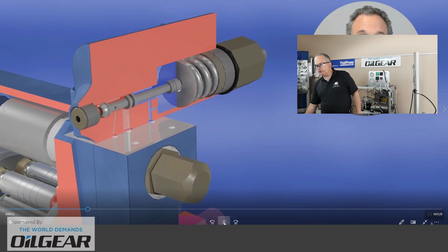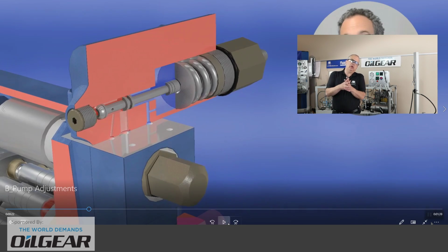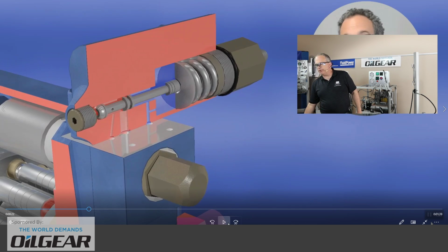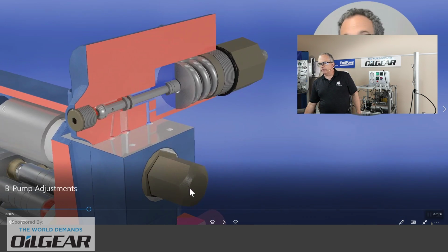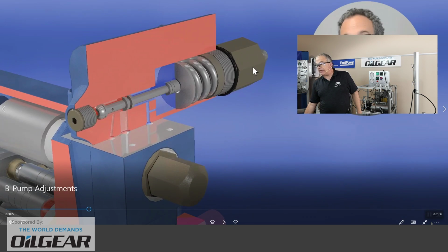It's very hard to demonstrate it perfectly in that a lot of these things happen almost instantaneously, certainly within a small fraction of a second. So if we cut open to that pressure compensator that we saw in some of my photographs as we were getting underway, what we will see is a very small spool, only the diameter of a pencil, working against a fairly stiff spring that was adjusted by you, if you're the maintenance technician, to a certain pressure.